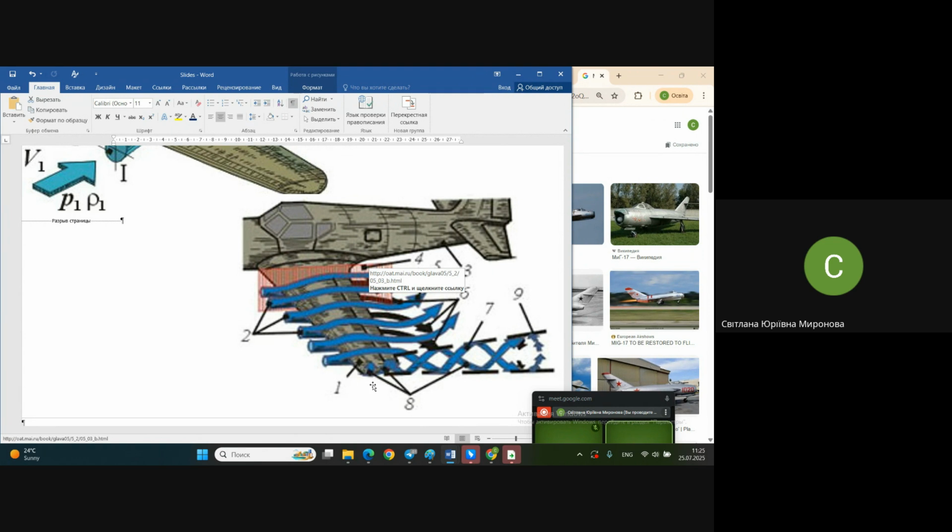And that is why, like it was in the Fowler flap, the higher pressure tends to move air up over the wing. And in this case, of course, we have a problem of vortex here. Imagine that some portion of air is additionally streaming in this direction. And vortexes and drag will be the result.